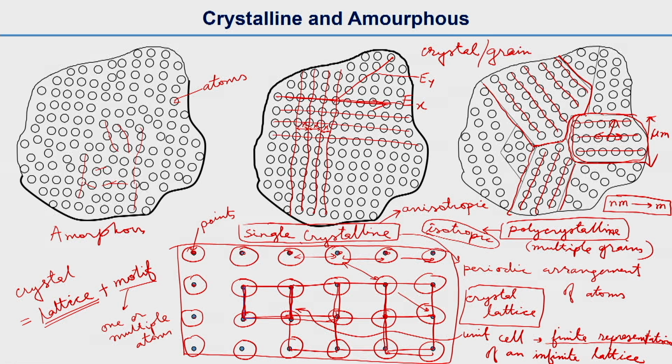But there are other cases of anisotropy that you can learn, like orthotropic material and transversely isotropic material. Also, if you take a single crystal of other crystal systems, like single crystals of cubic, tetragonal, and hexagonal crystals, they all have different kinds of symmetries and their anisotropy is very different from each other. So they are not isotropic. If you take a single crystal, they are anisotropic, but their anisotropy is different. Cubic crystal is different than tetragonal, tetragonal is different than hexagonal.